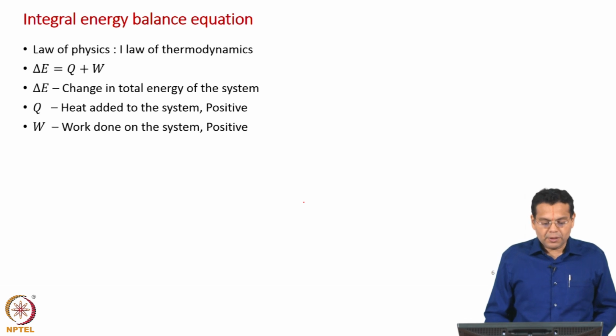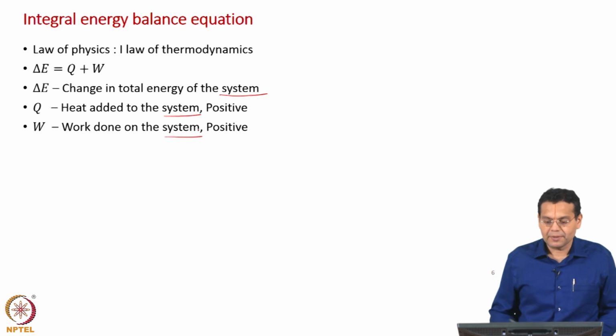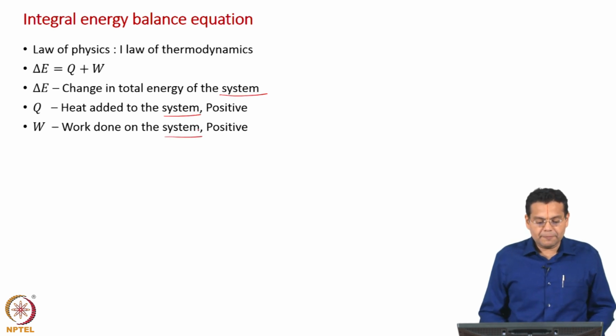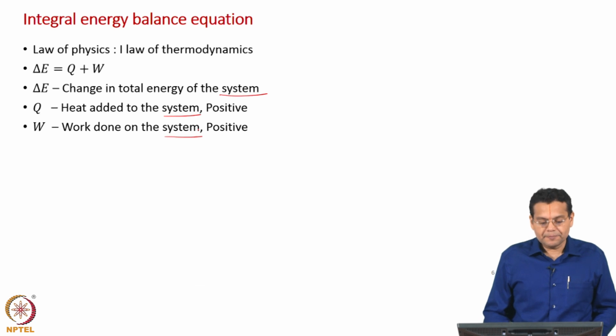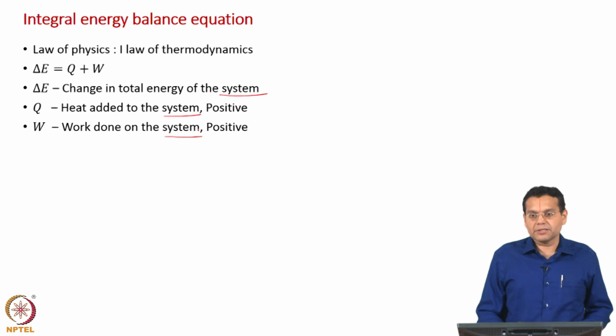Few points to be noted. First, all terms refer to the system, and in terms of sign convention, heat added is positive, work done on the system is positive. Okay. For heat added, the sign convention is universal, but for the case of work done, the sign convention is not so universal.